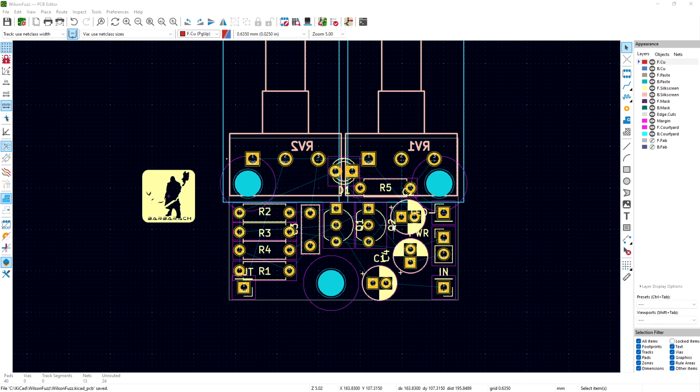For us, this is analog signal mostly, and what we need to do is have slightly wider traces than what you get in digital, and try to keep them as short as possible. Now, some of them are not really carrying any signal, like for LED, so that doesn't really matter.